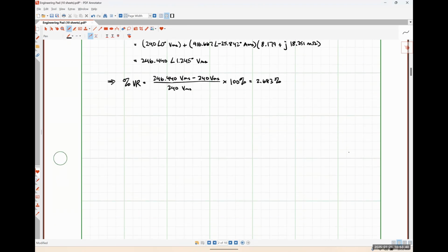So let's work one last thing here really quickly. I'm mainly adding this because once we get into our machinery, we're going to be talking about efficiency a whole heck of a lot. So many of the things we're going to be talking about with our rotating machinery are going to be related back to these transformer equivalent circuit models. For what it's worth, an AC induction motor is literally just a transformer where we allow the secondary to rotate. This will help lead us into that.